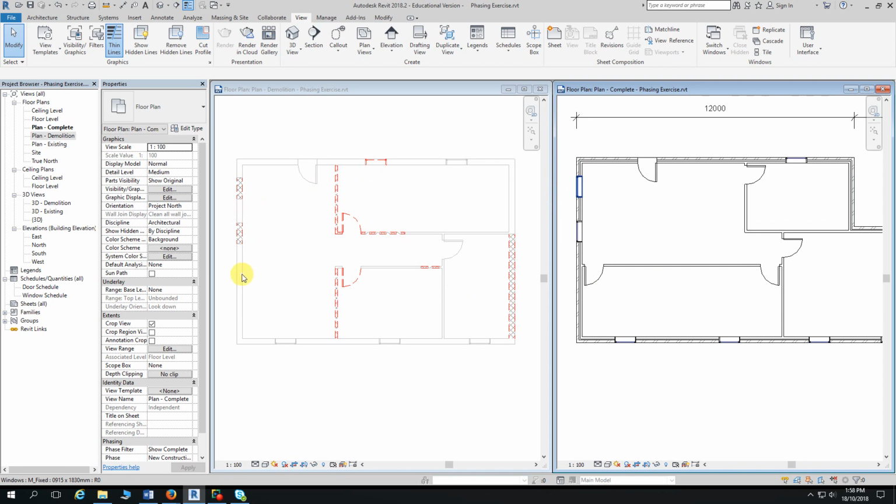Remember, this is an existing wall, and we've added two windows to it. So to add the windows, what do you have to do to the wall? Knock a hole in it. So that is classified as demolition. Creating the opening in the existing wall is classified as demolition.